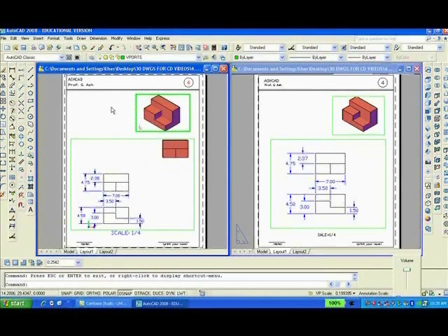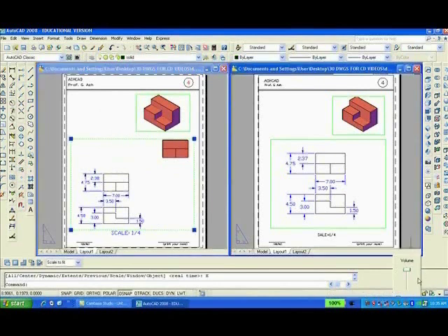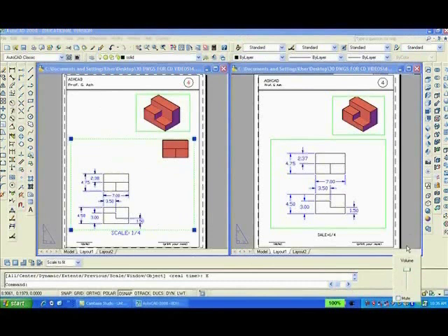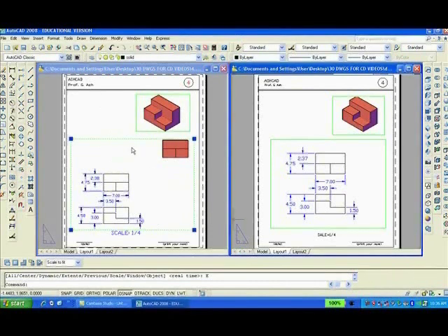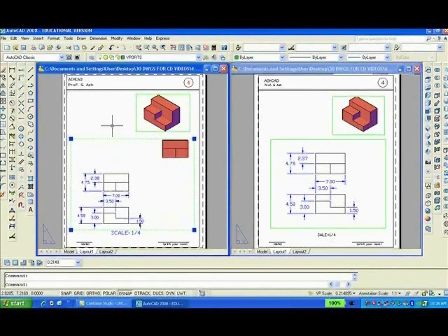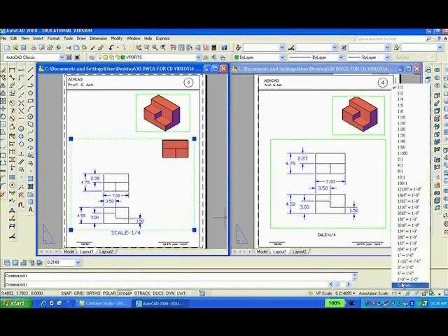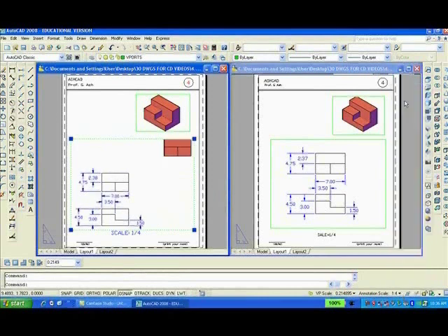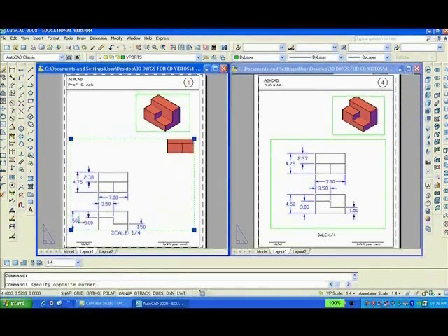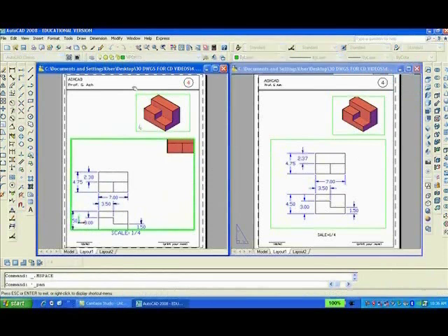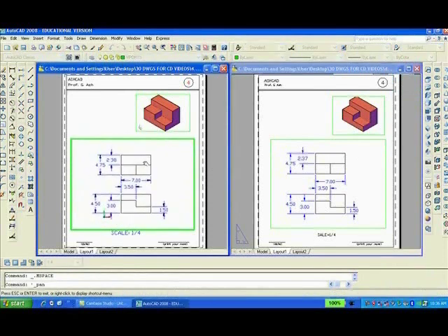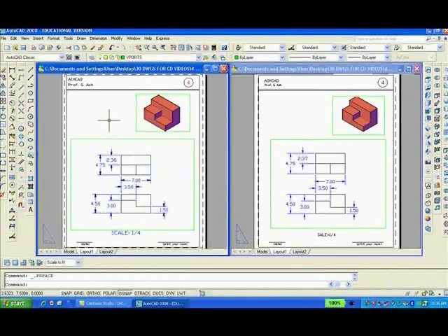Double click outside to get into paper space. Click on the large frame. That's in my way here. Okay. I want to go down, make to the annotative scale, and make it 1/4. Double click inside, then pan. Looks okay. So double click outside, get into paper space.